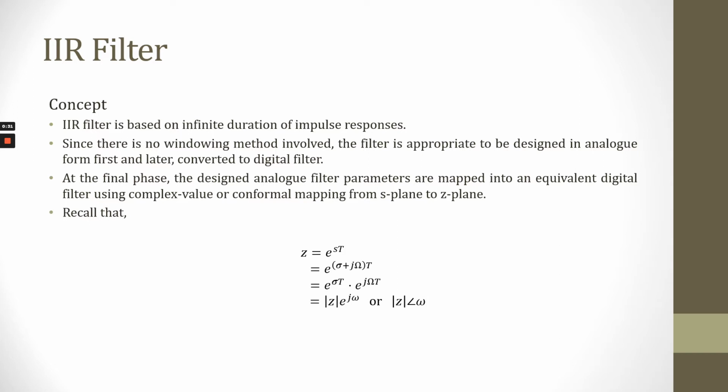There are two general approaches used to design IIR digital filters. The most common is to design an analog IIR filter and then map it into an equivalent digital filter, because the art of analog filter design is highly advanced. Therefore, it is prudent to consider optimal ways of mapping these filters into the discrete-time domain.